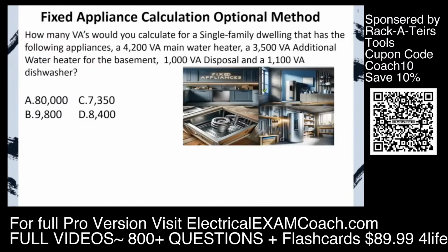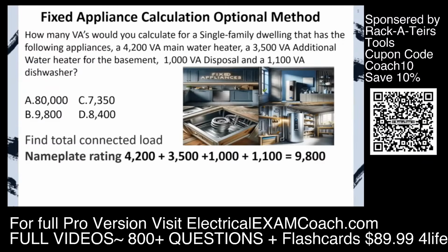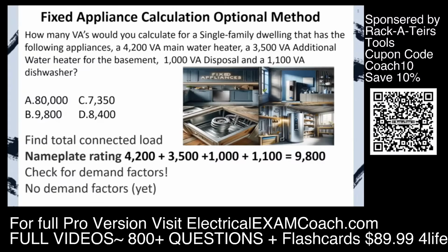How many VAs would you calculate for a single family dwelling that has the following appliances? A 4,200 VA main water heater, a 3,500 VA additional water heater for the basement, a 1,000 VA disposal, and a 1,100 VA dishwasher. First thing we're going to do is find the total connected load. With the optional method, we're going to take the nameplate rating of all these appliances. Now, let's check for demand factors. There are no demand factors yet at this portion of the calculation. All we're going to do is total up all these appliances, and then we'll apply 1 general demand factor in just a little bit. And we select B. Great job.